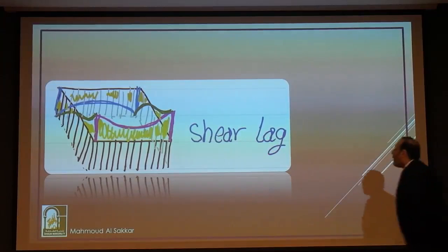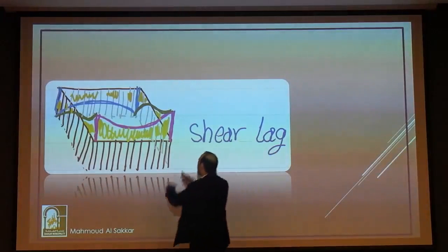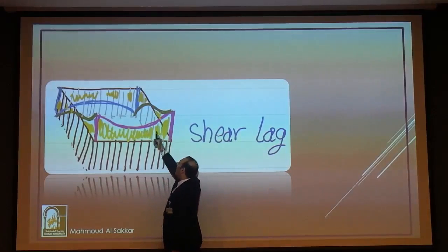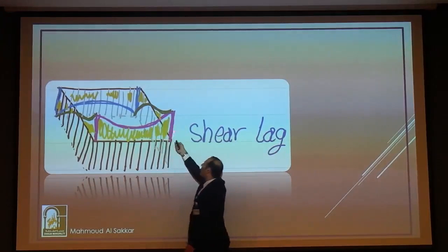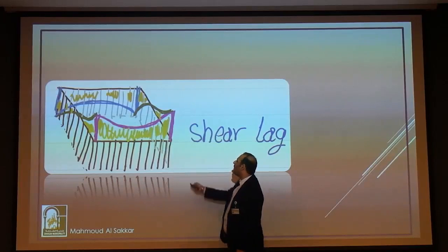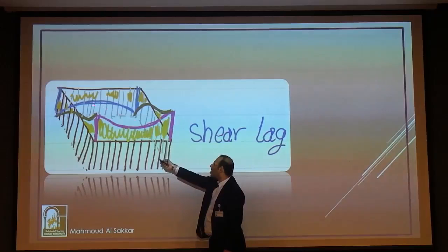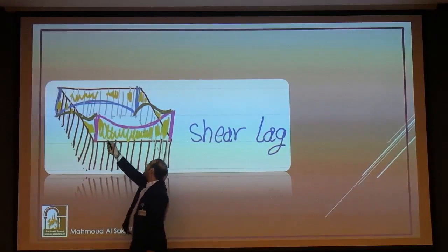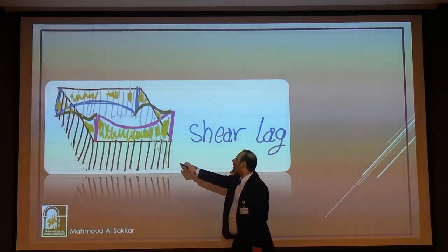Very simple. Look, we have, for example, a moment coming from here, the earthquake itself or the wind. We will have resistance here: tension here and compression over there. Tension here and compression there. But what about this column? The maximum tension here, what about compression here? It's not going to be a straight line. There is no straight line between this point and that point. It's going to be some curve like this one.